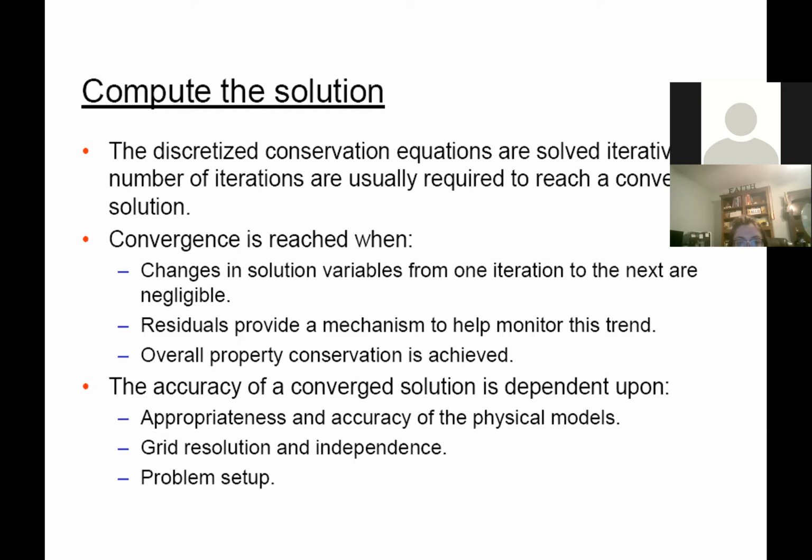Okay, so when you do steady state simulation in Fluent, it requires the iteration process. Fluent will stop the iteration when the convergence criteria is reached. So in that sense, you need to specify a convergence criteria. Otherwise, when is Fluent going to stop, right? Usually we use relative error as the convergence criteria. We say, if the relative error between this time and the previous time is less than, let's say, 10 to the negative 4.